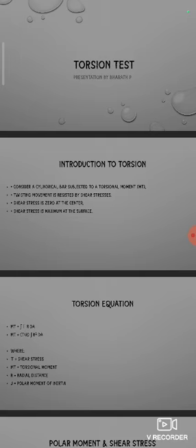The maximum shear stress occurs at the outer surface only. This behavior is very important in the design of shafts, axles and rotating machine parts.